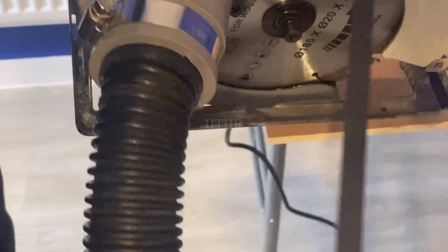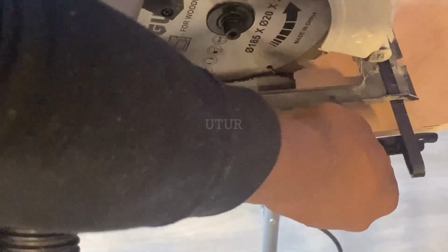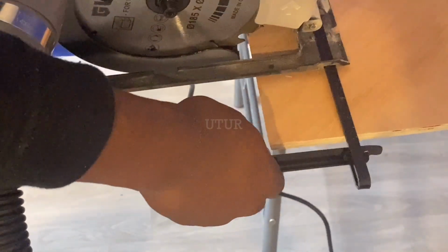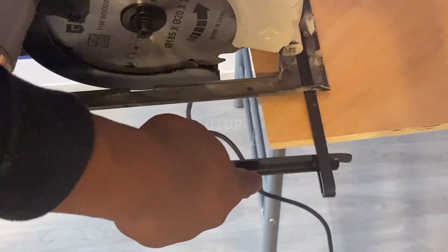If you do not have a table saw, you could deploy the use of a parallel guide or a rip fence to make repetitive, accurate, long, lengthy cuts. The parallel guide rides along the edge of the plywood. The parallel guide has got a scale on it that helps you determine the size of the plywood that you'd want to cut, strip or rip through. It's also got a lock knob that helps you lock the parallel guide into position.